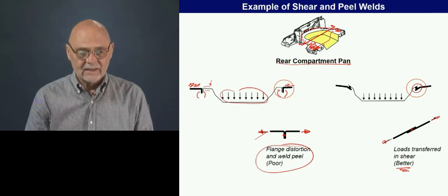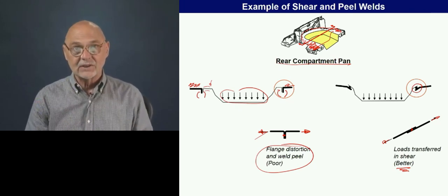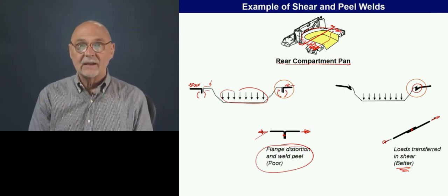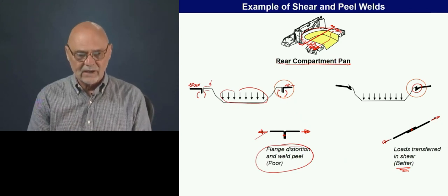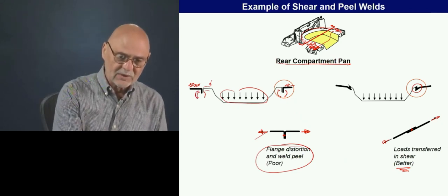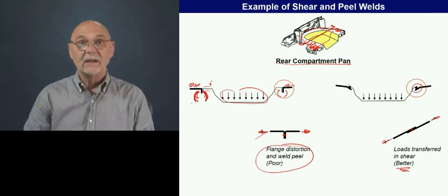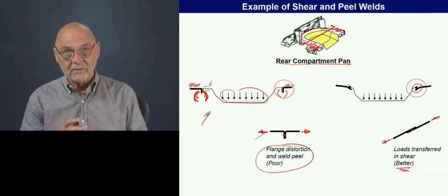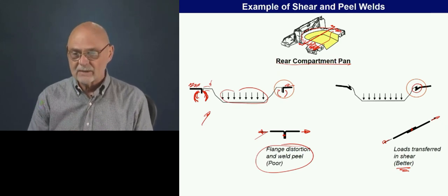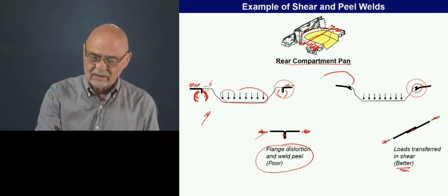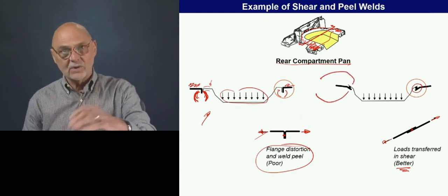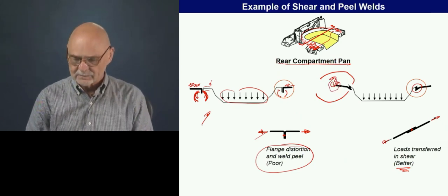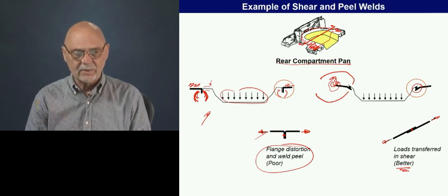Well, when you think about it, in the manufacturing plant we have to have nice access to these welds. We want small arms on the welders for their own rigidity, and to reduce the mass on the end of the robotic arm. These arms can be pretty small, very accessible to get into this area. So that's one reason why this might be desirable, not from a structural standpoint, but from a business standpoint. In this case, the arms would have to be fairly large to go around whatever other parts are in the way.